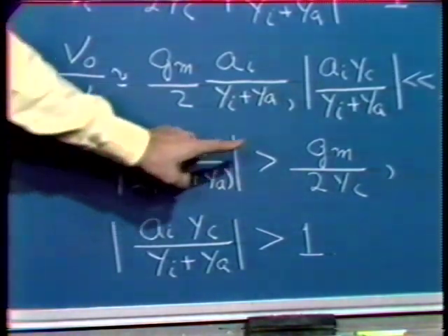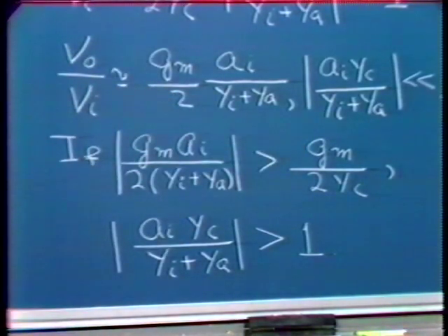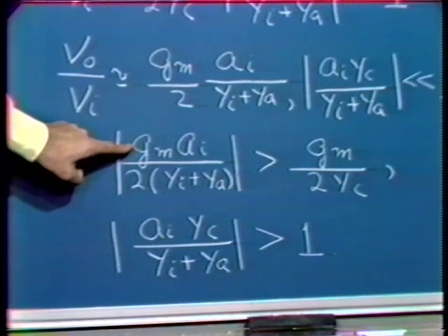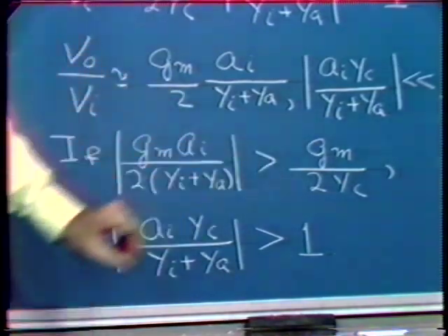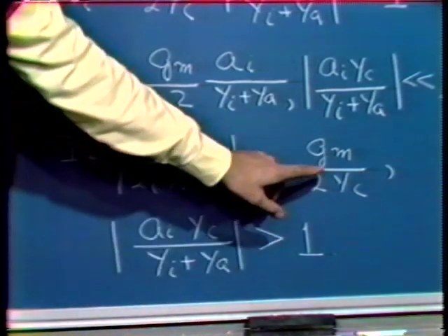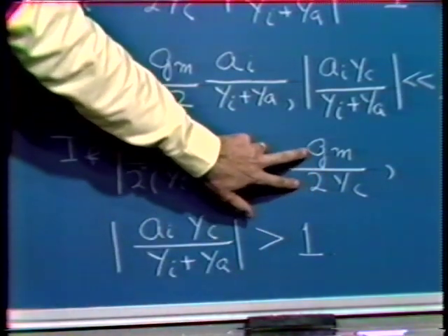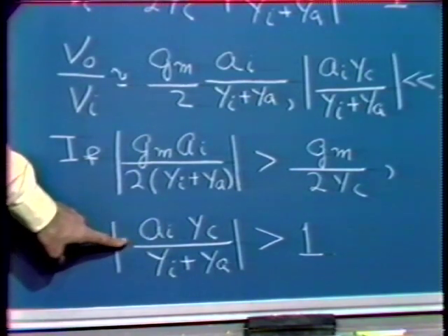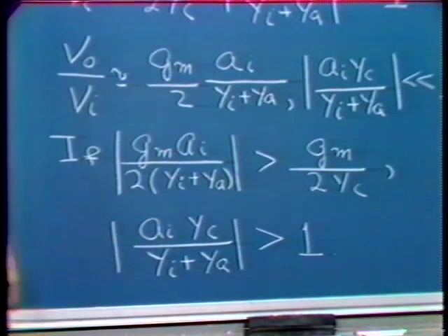We draw those two quantities on our usual Bode plot coordinates, and we look to see which curve is greater in magnitude. If, for example, this quantity, the open loop transfer function of the amplifier in the absence of minor loop feedback, is greater than this quantity, the implication, which we can get by simply multiplying both sides of this equation by the reciprocal of this term, is that the magnitude of the transmission around the minor loop is large compared to 1.